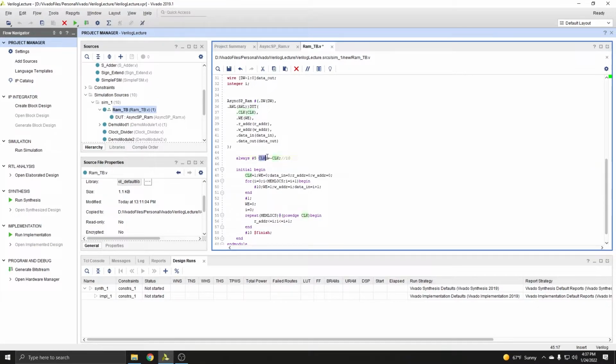And the code that is going to run, since it's one line, we do not need to use a begin-end block because it's just simply one line. You can simply do your clock signal, in this case mine's all caps, doesn't really matter, with a non-blocking assignment followed by the not symbol, which is the tilde on your keyboard, and then the same name of the clock signal. This basically is just saying every 5 time units toggle the signal to the opposite, meaning that, of course, you have 2 times this delay as the period.